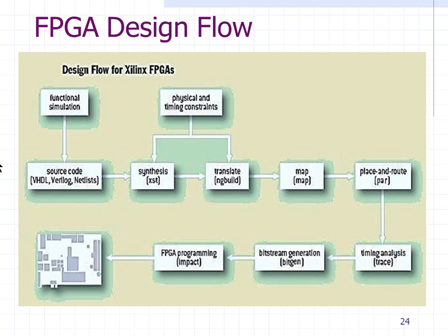So the design will be partitioned. Some part of your product will be developed as hardware, some part will be developed as software. If you take the hardware section, some part will be implemented as a chip, and the other part will be implemented on a PCB, a printed circuit board, using just regular discrete components. Whatever needs to go on a chip, they will develop the definition for that. That's called a design specification for your design. That design specification is the reference for your Verilog design, so you will write your Verilog design as per the design specification.